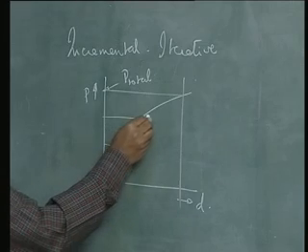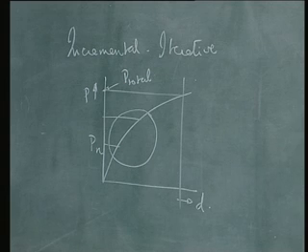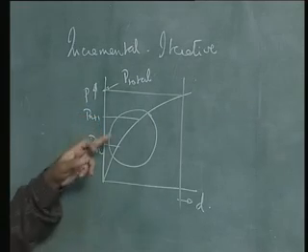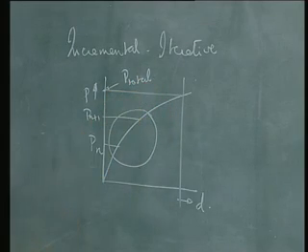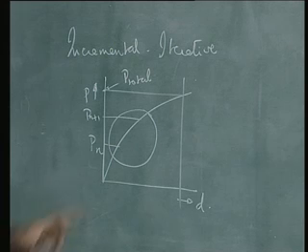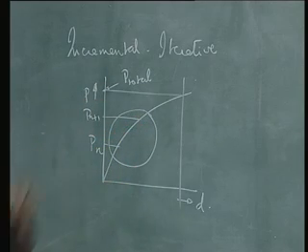Now, let us understand how this process of the Newton-Raphson scheme is applied to a particular nth step as we move from the nth step to the n plus 1 step. So, let us say that that is the nth step. I have a load of Pn, and I have to get to equilibrium at Pn plus 1. Do not tell me that I can just get to this point and do it, because I do not know this curve. I am trying to trace this curve. So, it is not that I know Pn plus 1 and can just go there. I am at Pn, I know everything about point Pn, I do not know Pn plus 1. It is only an illustration that I put this.